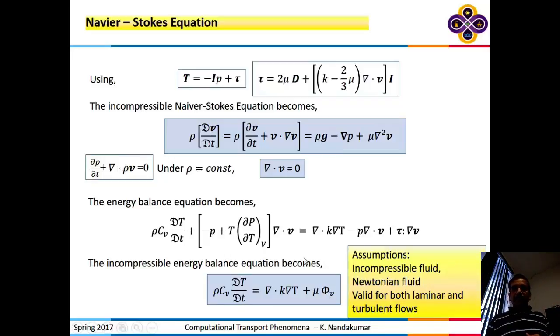And these two equations can be coupled. How are they coupled? Because the expansion for this D/Dt contains the velocity. It's an advective derivative. So the velocity will appear in here also. That term is what we call the convection term or advection term. The other one is called the diffusion term. This is where the analogy between fluid mechanics, heat transfer, and mass transfer is strongly similar. That was pointed out by the book by Bird, Stewart and Lightfoot in the 1960s called Transport Phenomena.